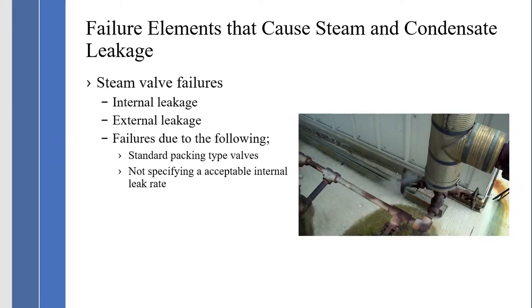Steam valve failures: internal leakage and external leakage. Two major points. We'll talk about the internal leakage. When you specify valves for steam, then we need to specify the leak rate inside the valve here. The second is the packing here.